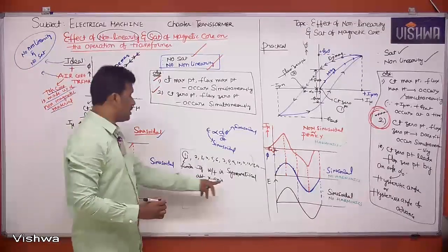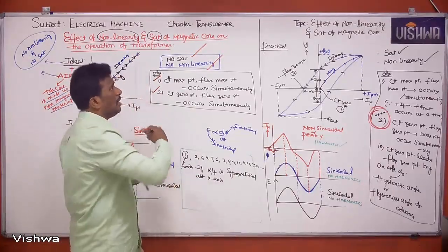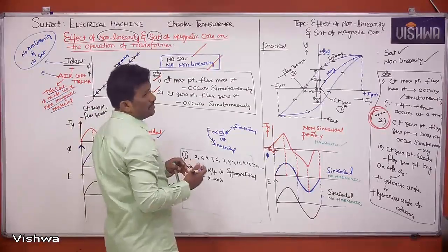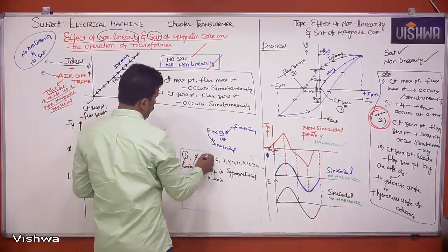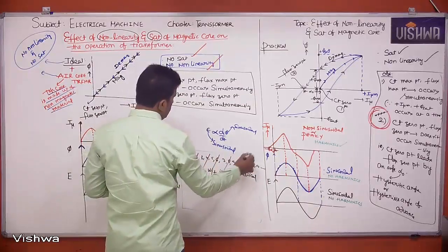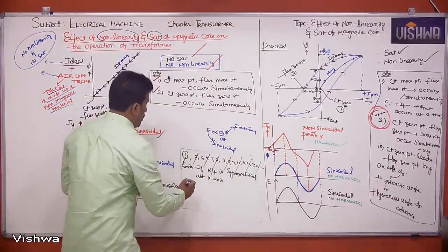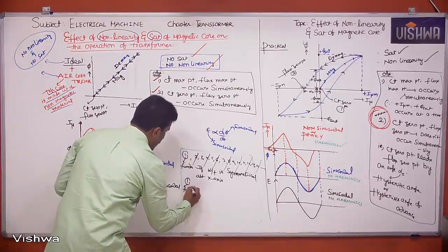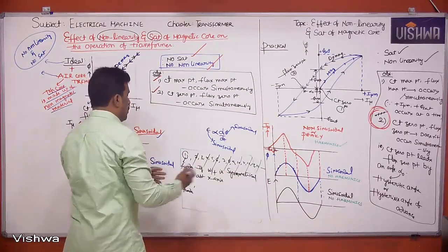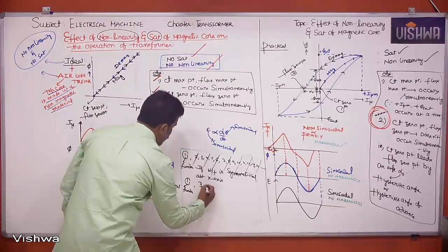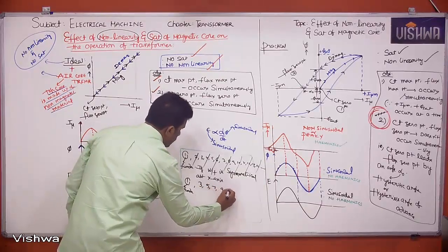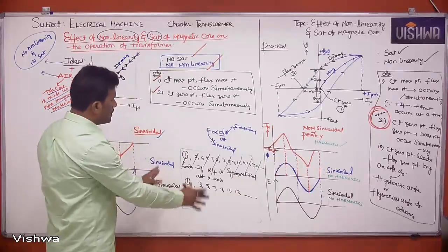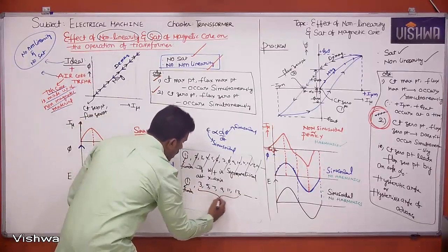Symmetrical about the x-axis means same magnitude, out of phase. If it is like that, even harmonics cancel with each other, that means 2, 4, 6, 8, 10, 12, 14 and so on. Next, this is about the fundamental. And if I cancel the even harmonics, what are the odd harmonics we are having? 3, 5, 7, 9, 11, 13 and so on. These can be called odd harmonics.